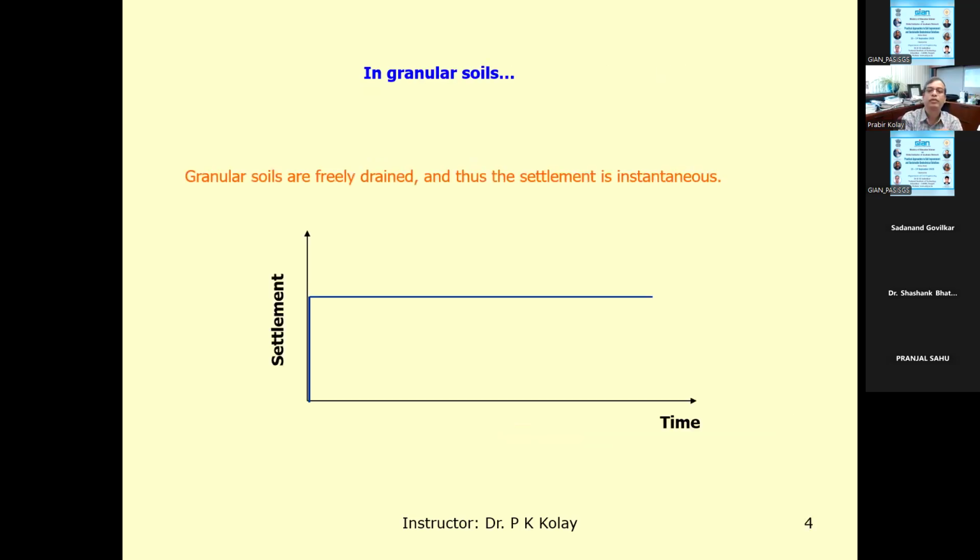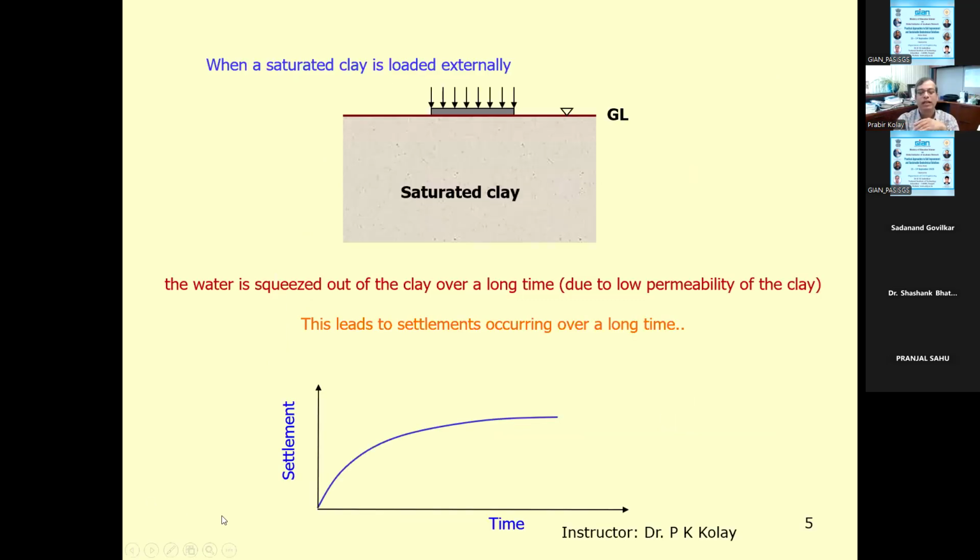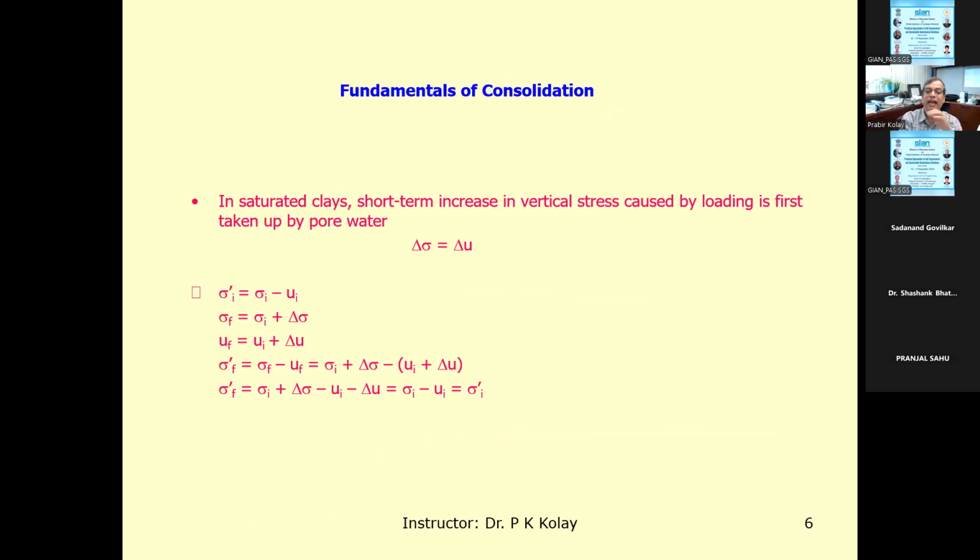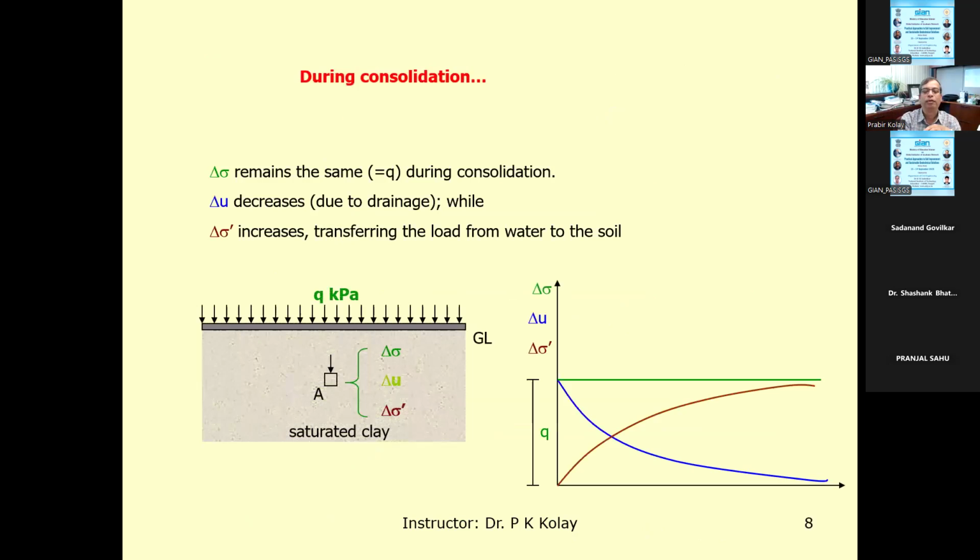In granular soil, what is happening? The settlement is immediate. But in a clay type soil, the settlement takes time, and then it is going to take place with time. Again, you need to look at what the pore pressure is.